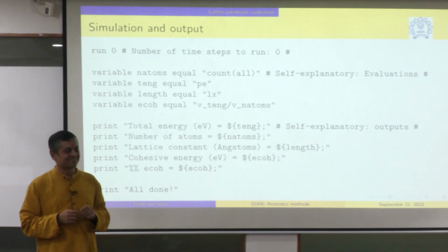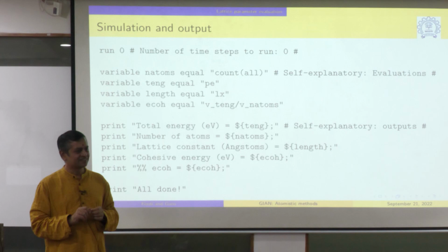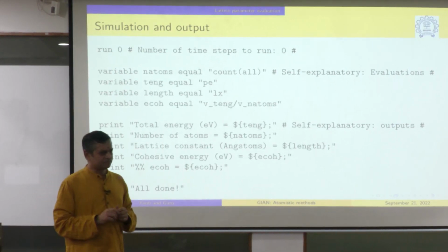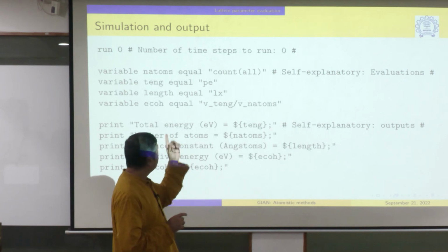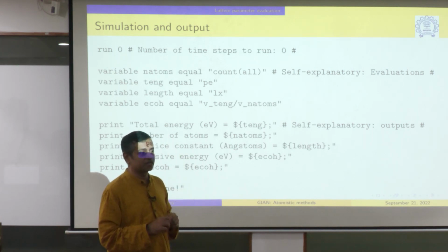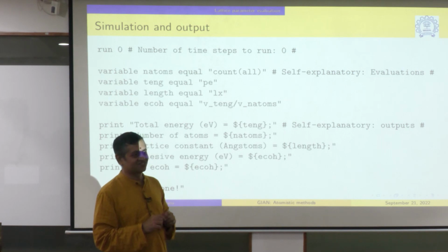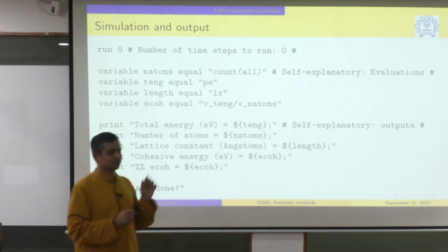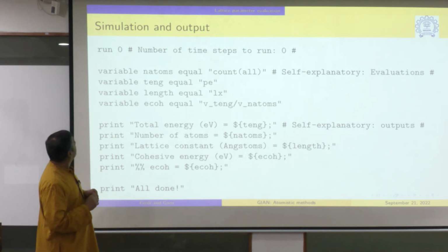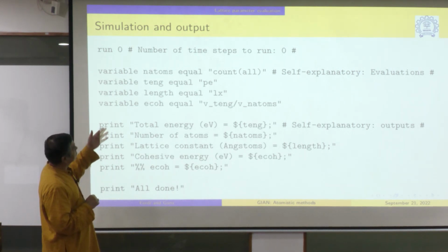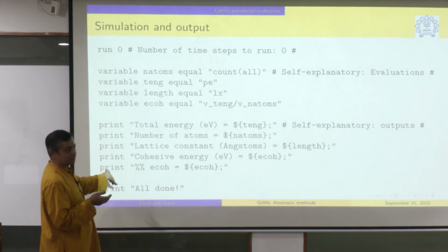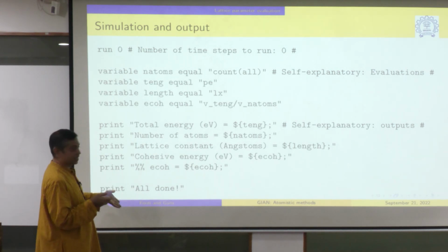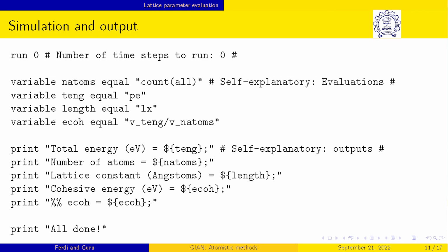Sir, another thing is that in the script as of now, nowhere have you given how many atoms you are using. No, I defined 1 unit cell and I did not replicate it, just 1 unit cell. It is a BCC, so it will have 2 atoms. There is no run; after the minimization we are just writing the data and exiting. When I show the script, I will also show how to visualize, but that is a very preliminary kind of visualization, not what is preferred. We will have a more detailed lecture on visualization later.